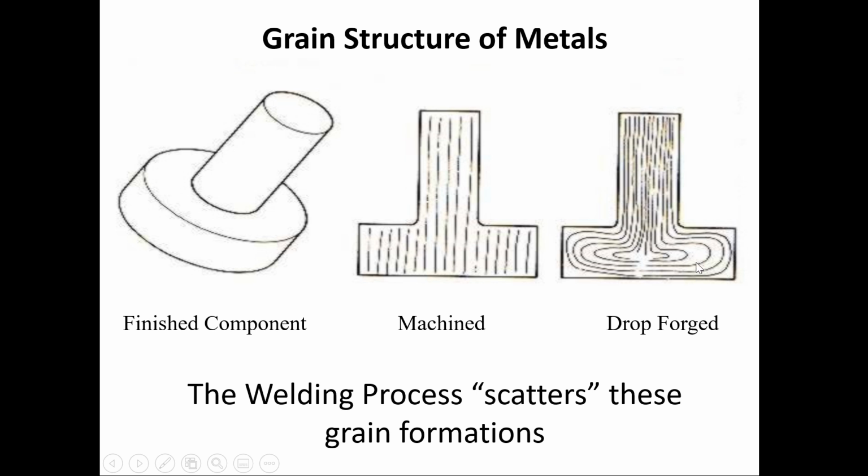As opposed to a piece of material that comes out and gets forged, and it's above its critical temperature, it's above its eutectic point from the carbon phase diagram, and we're going to push it around and forge it. We're using drop hammers and all kinds of different things. We're going to push it around while it's red hot. So when it cools off, we end up with a grain structure that helps us in strength. That's the idea. That's why you go out with all your wrenches and they all say drop forged on it. That means the grain structures are even throughout based on the shape of it. It wasn't machined out afterward.